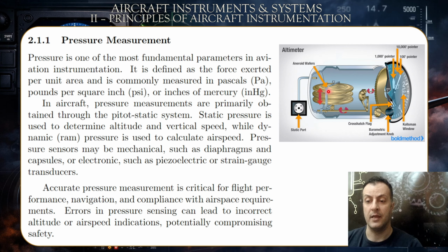diaphragm-like compartment. Now as the altitude increases, the difference between the pressure stored inside the diaphragm and the pressure of the surrounding ambient air at a specific altitude increases. So the air on the inside would start pushing, dilating, because of that pressure differential. It would start extending and dilating these aneroid wafers. As it dilates, it will move this rotor-like mechanism.